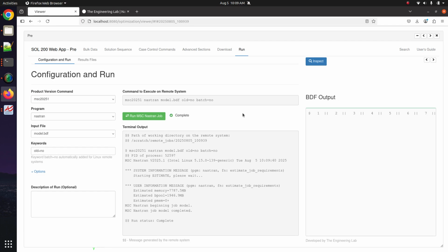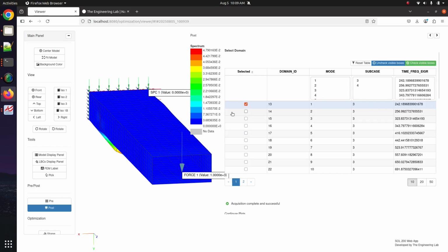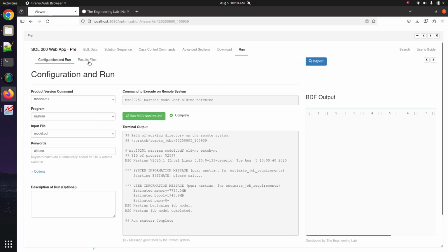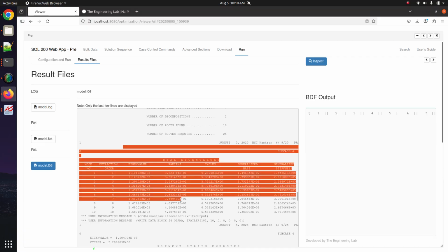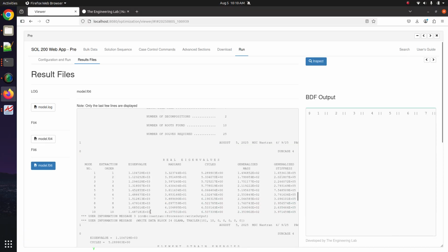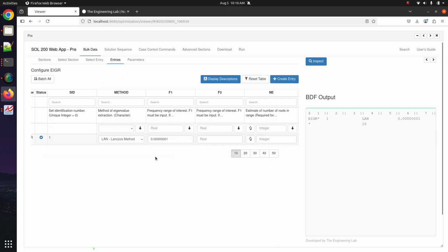So there are multiple places where you can look at the eigenvalues. Here, when you're at this table, you could look at this column in the table, time, frequency, or eigenvalue. Before, you'll notice that we have both positive and negative eigenvalues, but now you see we only have positive eigenvalues. If you go back to the F06 output, here's our table for subcase 4. You notice that the eigenvalue column only has positive eigenvalues. So that's the way you can control whether or not you get negative eigenvalues.